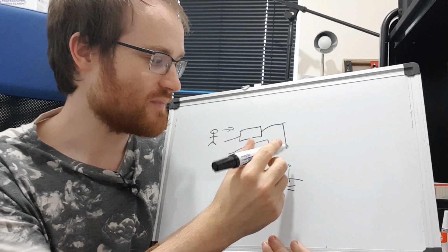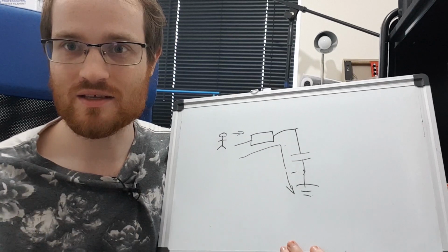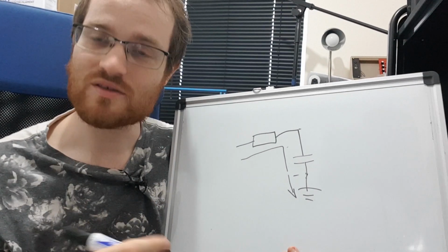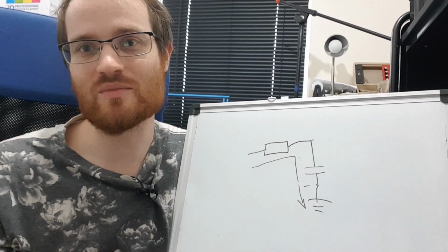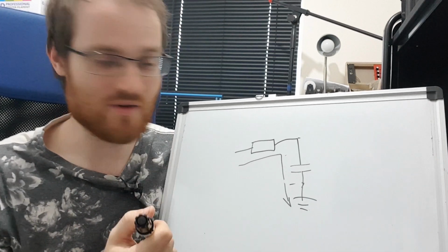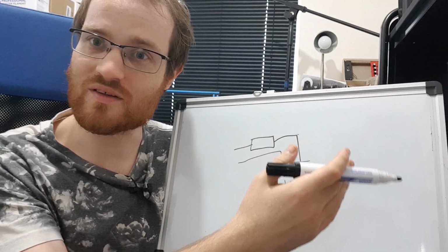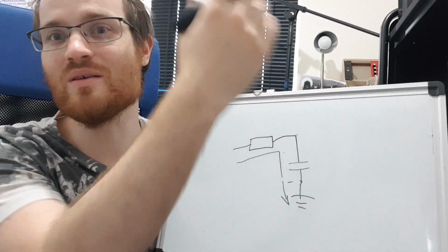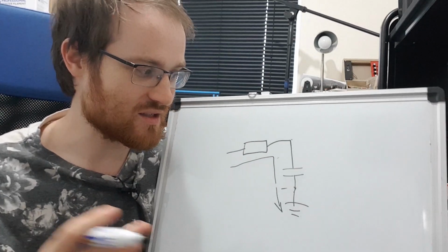And so now we look at it from the other side. So now we think, what's the worst case that an output impedance can get? Well, output impedances, we want them to be nice and low, so that we're not having to go, right, the thing it's driving has to be 10 times greater than it to get this nice ratio voltage divider thingy we spoke about a second ago. So if the output impedance of this is really high, then the input impedance of the next stage has to be really high, and then the output impedance of that stage is going to be high, so then the input impedance of the next, and you get this horrific exponential growth of impedances, and it's a real pain.